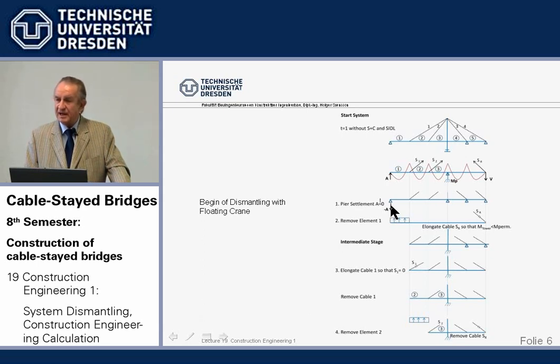Then we take out this support from our structural system, and then we have the next system which just has a cantilever here but no support anymore. Then we remove the dead weight, that's all there is. We have taken shrinkage and creep and superimposed dead load out. We remove the dead weight, means we apply it with a negative sign, if that's easier for you to think.